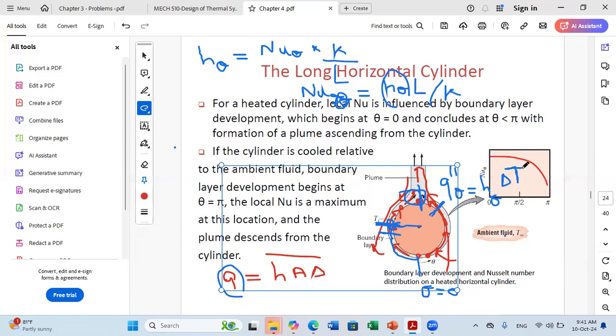But actually, whenever you want to calculate the total heat transfer, you need to consider summation. For this small area, I will call it dA, an elementary area, you multiply by h(theta) delta T. If you take another area, h will be different, etc. You do integration, the integral of q'' dA, in order to find the total rate Q, okay?